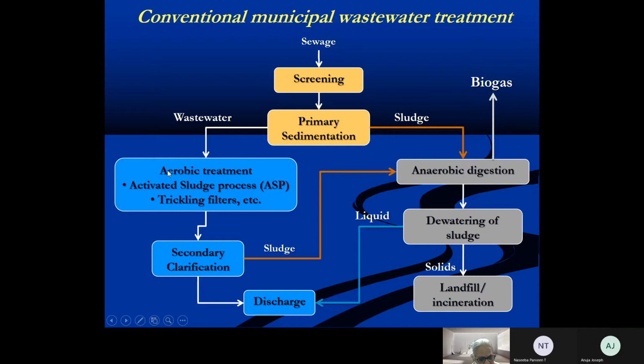So you'll be able to understand what aerobic biological treatment is. Now, because one of the end products is biomass, you need a method for removing that biomass, because that biomass is still organic matter and it's highly biodegradable organic matter. So that is what we call sludge. So we take the material from the aeration tank. From the aeration tank, it goes to what we call a secondary clarifier.